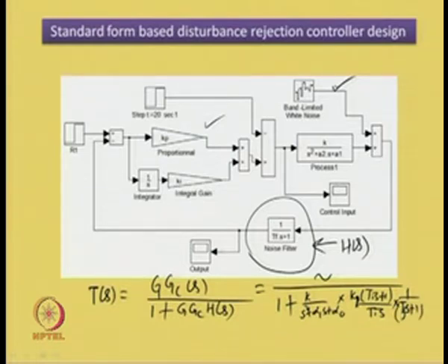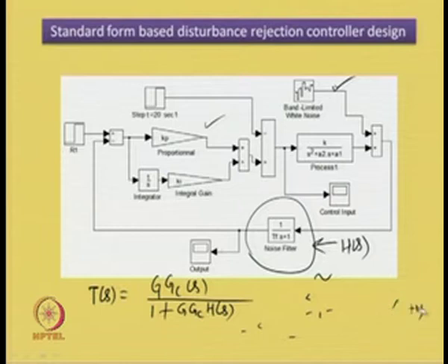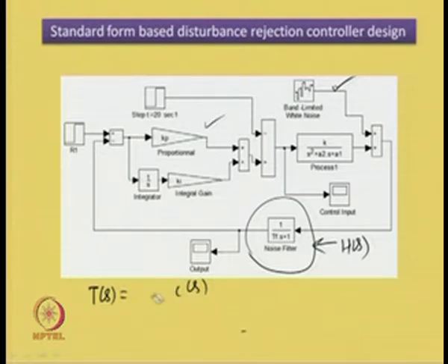So, when we approximate Tf equal to Ti, this approximation enables us to cancel one pole with one zero, thus giving us in the denominator terms like 1 + k Kp / ((s² + α1 s + α0) Ti s) only. So, that is where we have got a closed loop transfer function which is devoid of the Tf term.